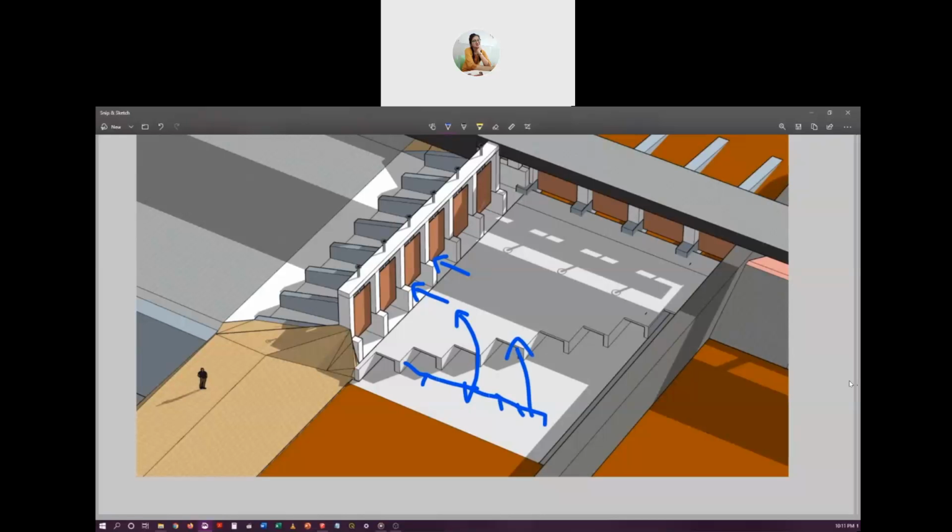Once we adjust the tunnel lengths so that this tunnel is the longest and this tunnel is the shortest and so on, then because the water velocity is in this direction, a major part of the lower portion of the flow will enter these tunnels, and therefore along with that, sediments or the silt will be trapped inside these tunnels.